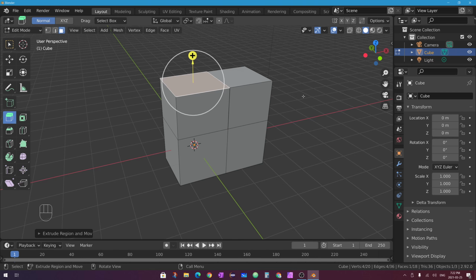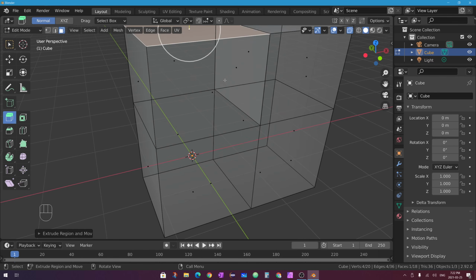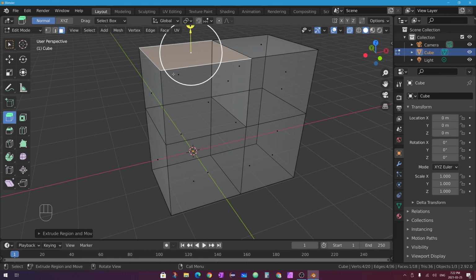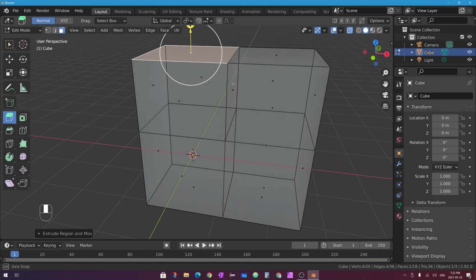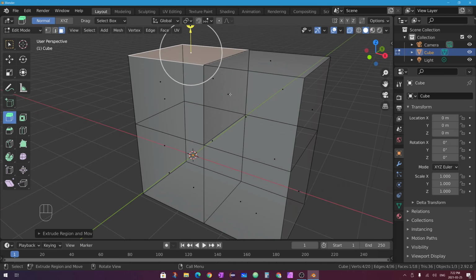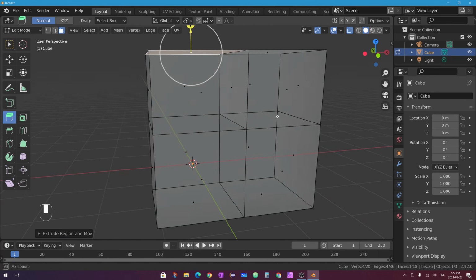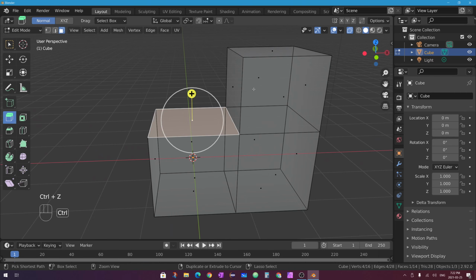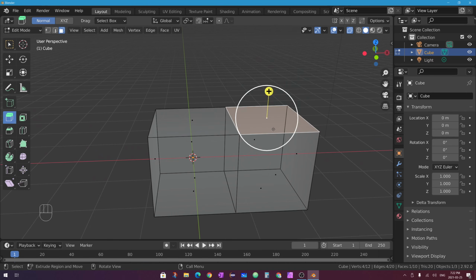I can actually see internal geometry a little bit easier on my screen. If I turn on this button right here, it's called X-ray mode. And with that mode enabled, I can see through my mesh to the other side. And when you're in face select mode, you will see dots or little squares on all of the faces. And if I orbit around, I can tell, hey, there's actually an extra wall. There's actually 2 extra walls, extra dots in the middle of the shape. It's not good.